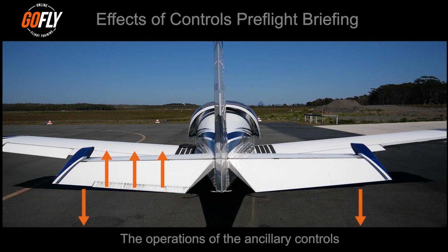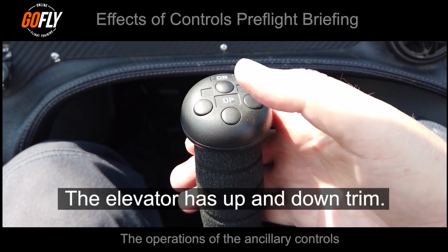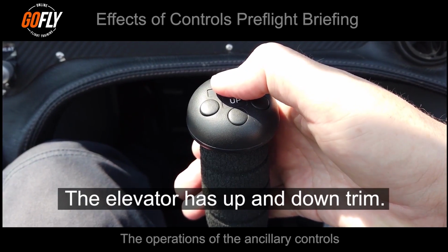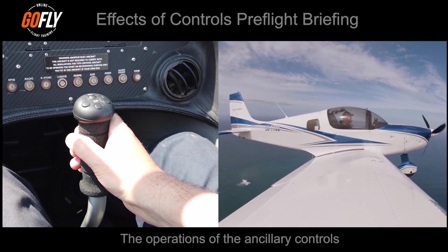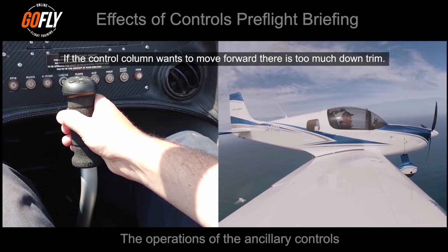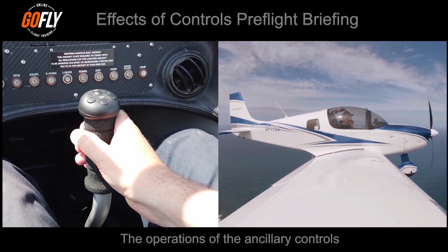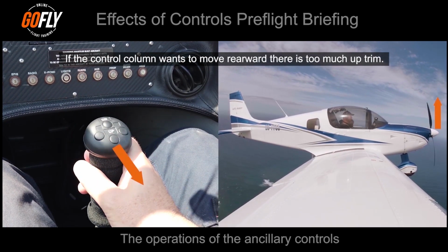Think of the trim tab as producing an opposing force to that particular control surface. From the cockpit, all the pilot has to remember is that you have up trim and down trim. If the pilot feels pressure on the control column and the control wants to move forward and the aircraft wants to pitch down, then there is too much down trim. If the aircraft wants to pitch up and the control column wants to move rearward, there is too much up trim.